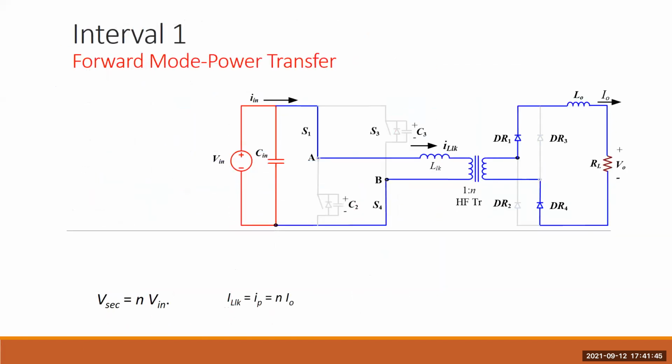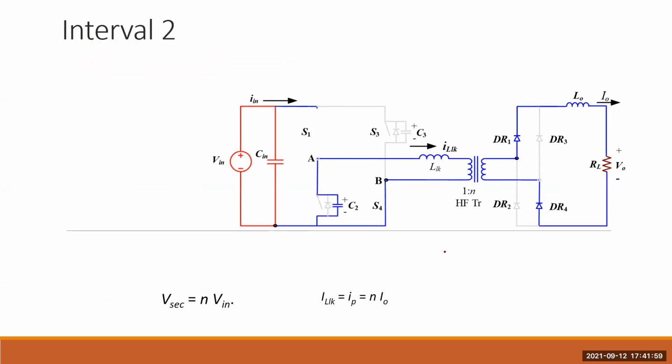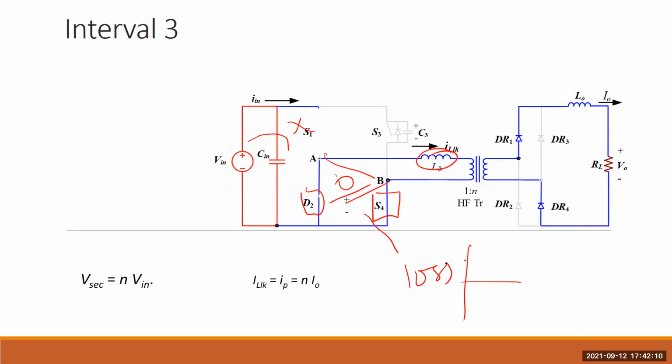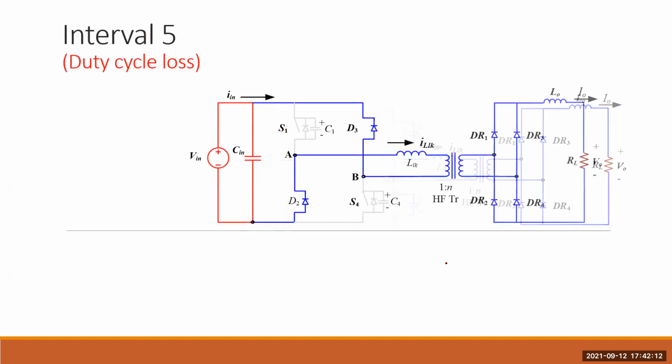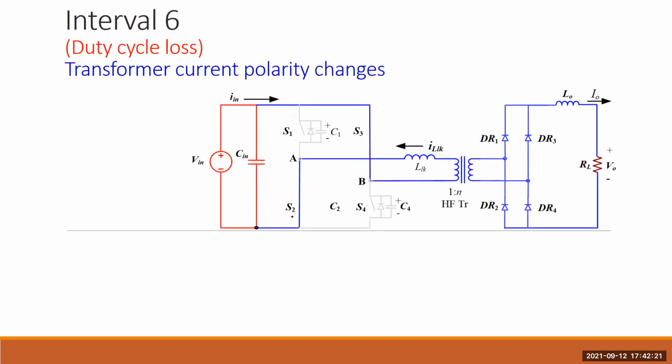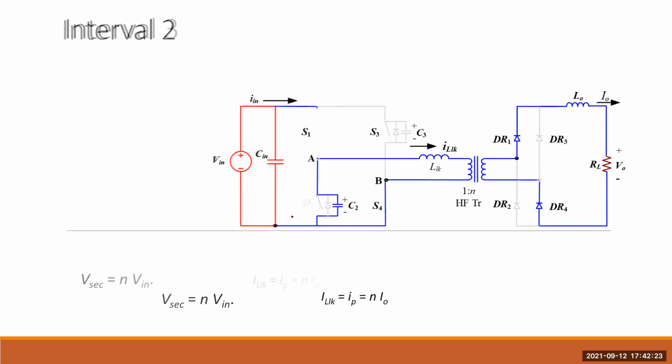When the positive voltage is applied across the transformer, Vin, flux will start rising, and after that you can see it is 0, then flux is constant. It remains constant further, and now negative voltage has come, due to diode conduction and then due to the other pair of switches. Then the flux starts going down after that.